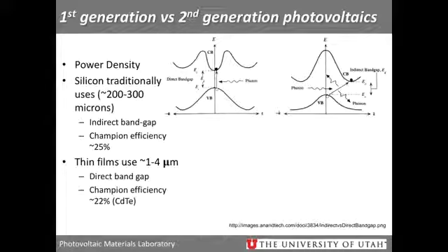So in order to absorb a photon of light, you not only need a photon with energy higher than the band gap, you need a momentum shift. That generally comes from some phonon transition that imparts an extra shift in momentum to the excited electron. And because of that, silicon has really low absorption coefficients. So essentially, you need a lot more material to absorb the same amount of light.